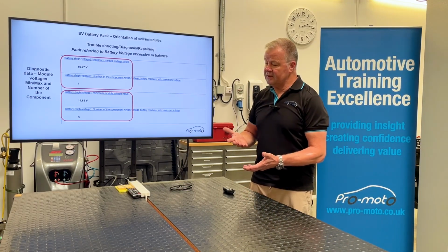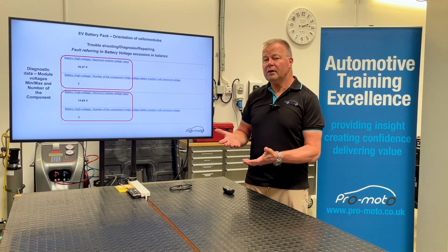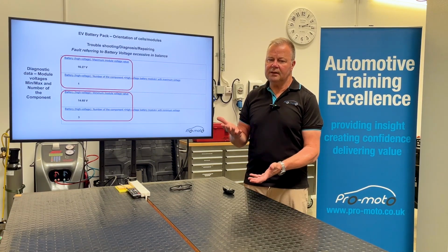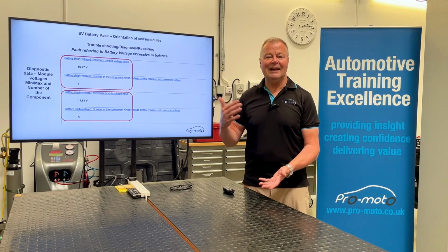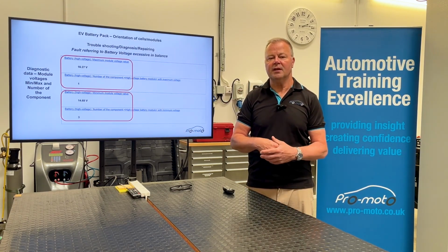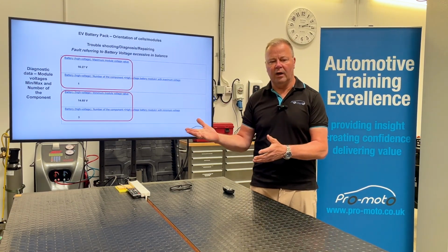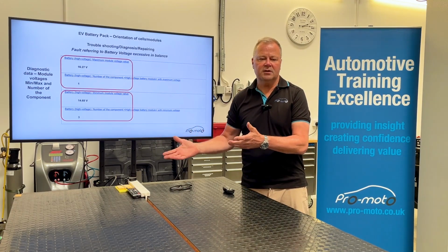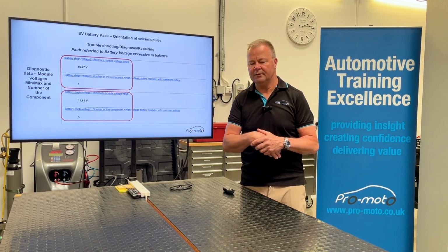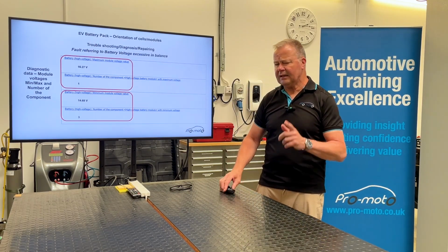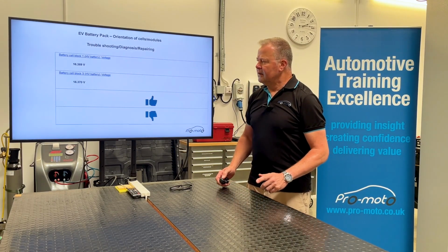And as you can see from this example, there are quite wild differentials between module 1 and module 3 as far as voltage is concerned. And clearly, this would give us a problem within the battery. So that's step 1. It tells us we've got some imbalance in the battery and it's pointing towards a couple of modules within that battery. Okay, let's take it one step further.